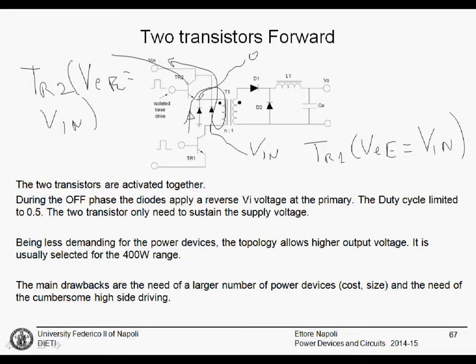However, we are paying something. We are paying one more power device and one more diode. These are components that have their cost on the topology. It's not free. However, you can see that small or large modifications to the circuit, leaving most of the things unchanged, are just changing the voltage requirements on the circuit and changing the power.